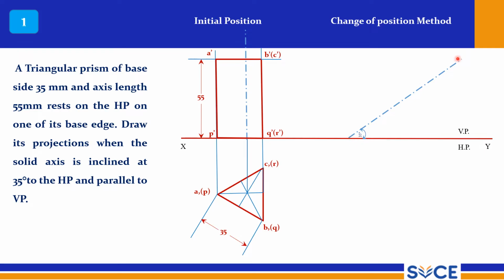So that way you can proceed, because it will be very simple if you use this trigonometric concept. Very simple. And you can draw the baseline. So this baseline QR is somewhere here. And you should mark this point, this distance should be maintained, here to here. So this is the line I am reproducing, and the entire view I am going to reproduce here at 35 degrees. The entire view I have reproduced here, with the same dimensions, whatever dimensions I have, the same dimensions I need to adopt here.